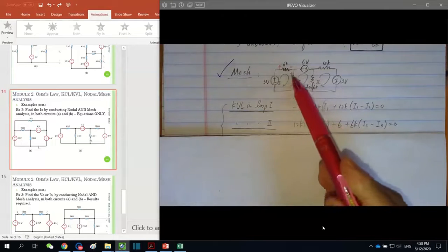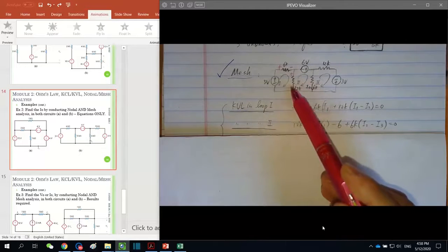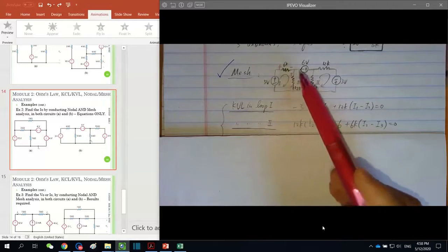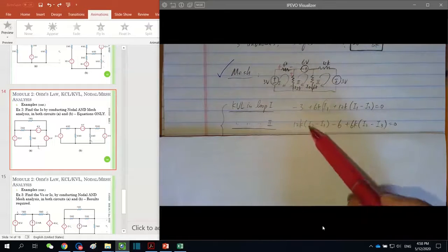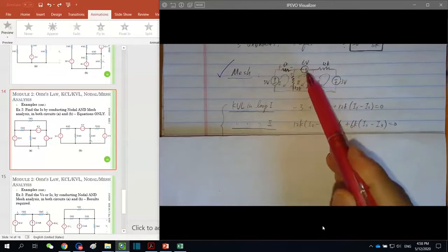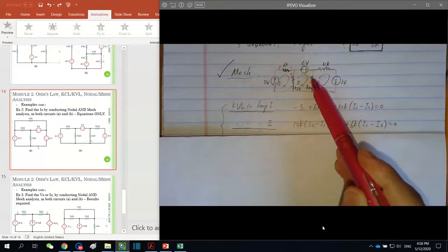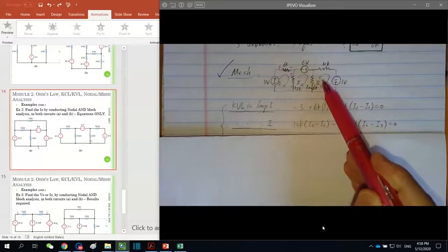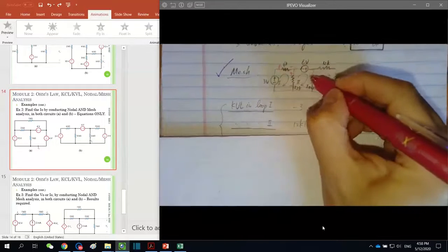Loop 2 in the middle here. So we have the same voltage here. However, because of this rotation direction, we come across negative polarity first, followed by positive. So negative 12K times I1 minus I2, equivalent to 12K times I2 minus I1. And then negative, positive for 6 volts, so -6. And then plus I2 minus I3 times 6 kilo ohm equals 0.